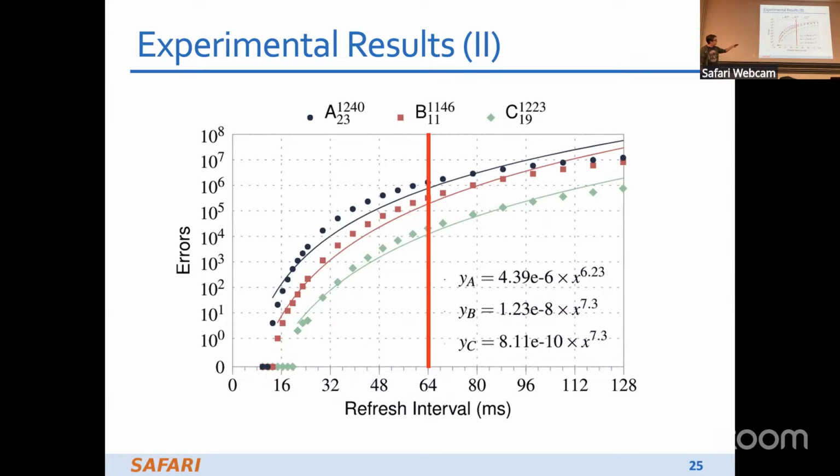However, as you may note, the errors also still appear at higher refresh intervals, but also at lower refresh intervals, and they only disappear at around a quarter of the standard refresh interval, which is a considerably faster amount of refreshes and would somewhat impact the performance of the module, because whenever the DRAM is refreshing, it cannot be accessed for read and write.